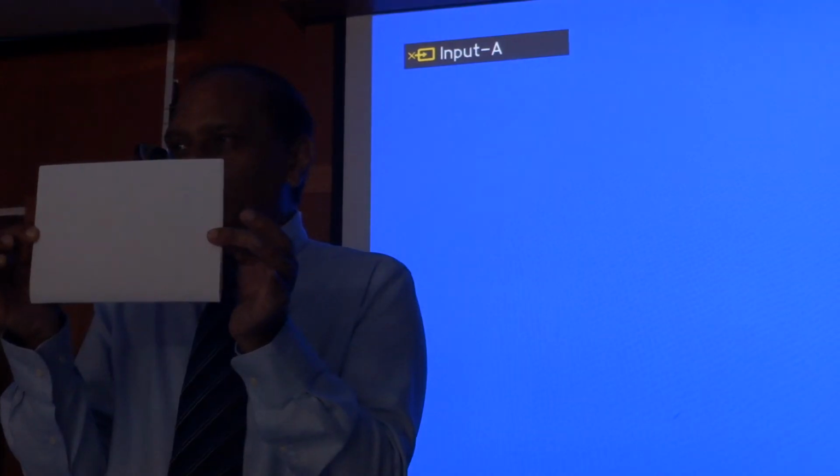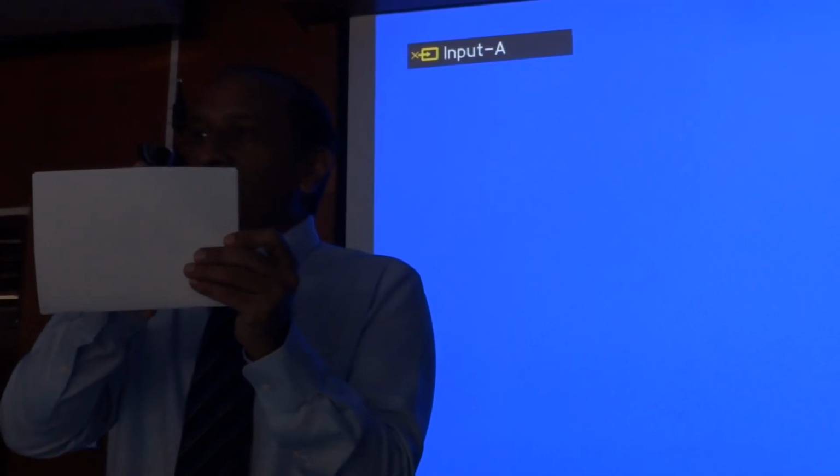If it's a beam like this one, very rigid beam, right? Moment of inertia is very high, I equals d cube by 12. To produce very small deformation, you will need a very large moment, correct? To make a small deflection, you will need a very large moment. True? Then compared to this one, very small moment can do that.